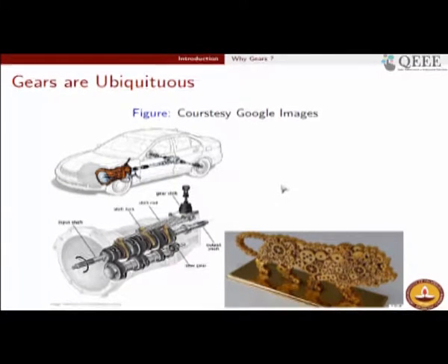The power requirement of the machine is met by the engine, but the torque-speed balance requirement cannot be met by the engine, at least from an economical standpoint. So, from an economical standpoint, it is imperative that the engine be clubbed along with certain gearing systems such that the diversity of the torques and the speeds that can be tapped through that engine system increases manifold.